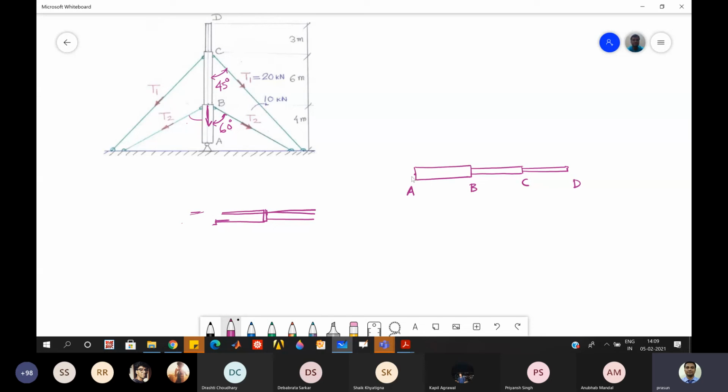So you'll have one load coming here and another axial force coming here, and at this particular point there will be some reaction this way. I can write this as RA, and this one as F1 and this as F2. Can you tell me the values of these forces F1, F2 and RA? If you simply draw a free body diagram, you'll be able to find out.